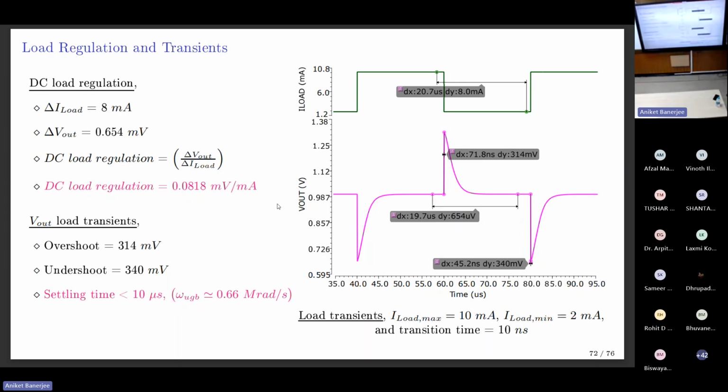So it is all tied to what the load circuit wants. If the load is a very good phase noise VCO, I'm concerned about the supply lines, so that's where I will work on a low output noise LDO. From the phase noise spec, I tie to the Vout noise spec. From the Vout noise spec, you have to match to gm, ro, ID/W, and fT, these parameters of the MOSFET. Once you do that, the tech plot will take over to give you the W/Ls to get that noise performance.